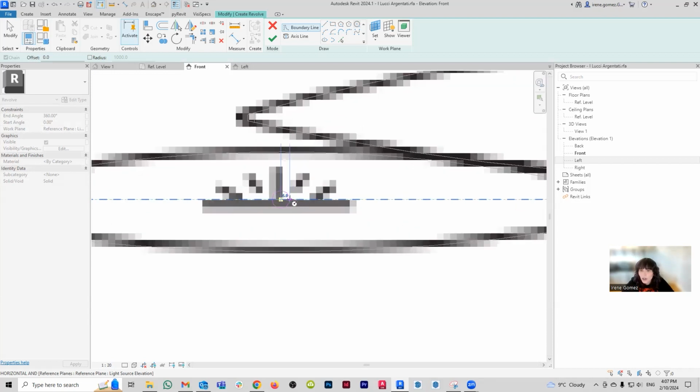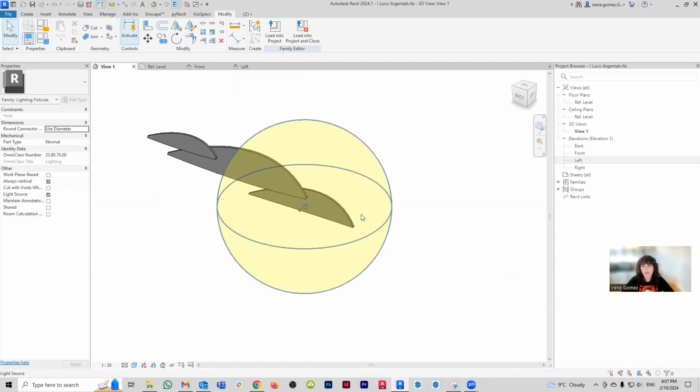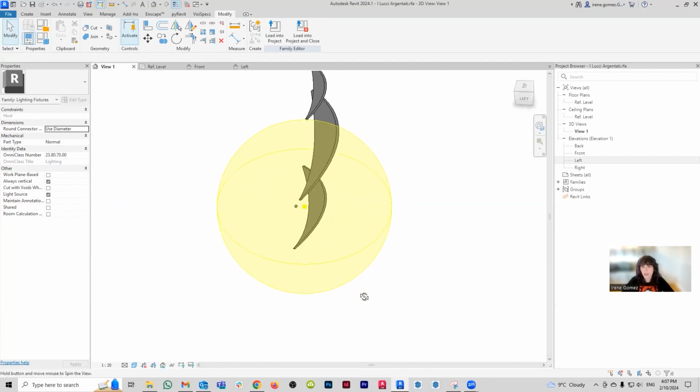I think 5 should be enough. Now, because it's a revolve, I'm going to cut it in half. I'm going to go SL to split, and then trim, trim, trim, trim, trim, trim. And then I'm going to choose my axis line to be this one here, and lock it there. And when I finish, I'm going to have a little sphere, there you go, where my light is.